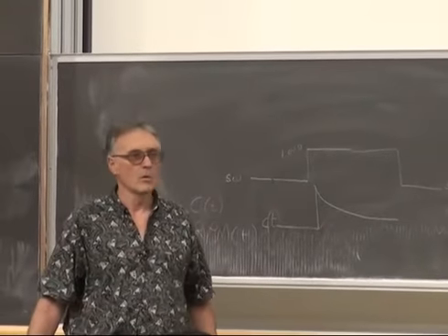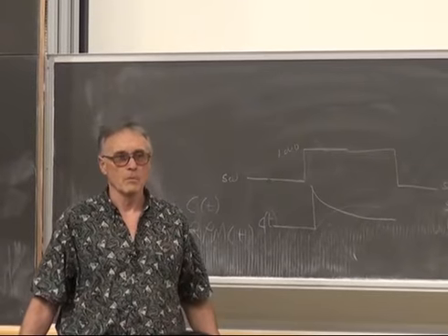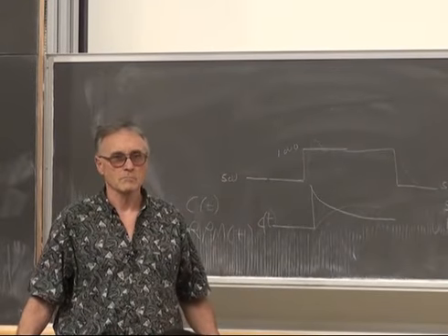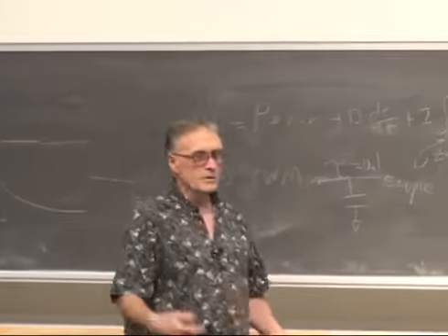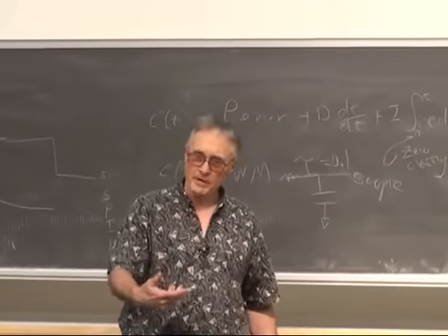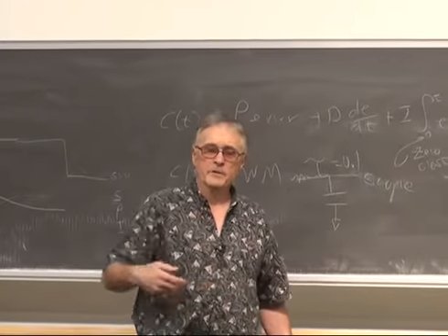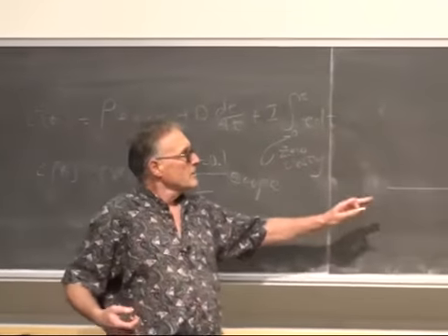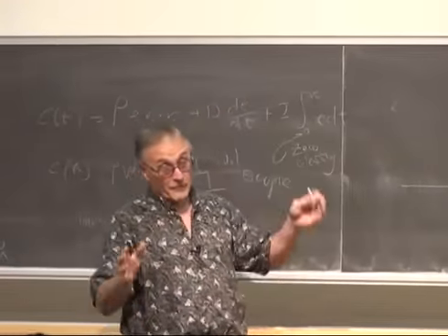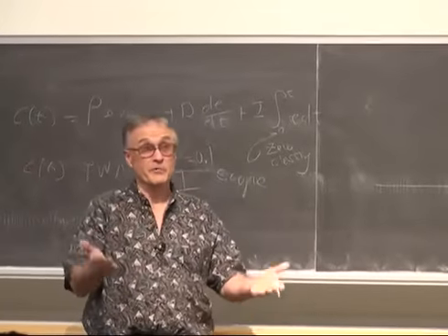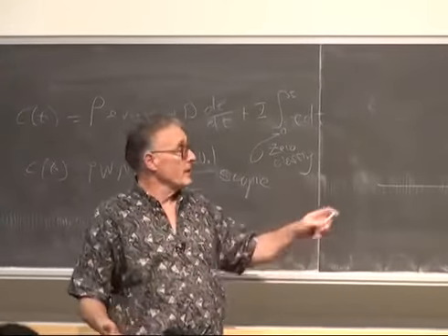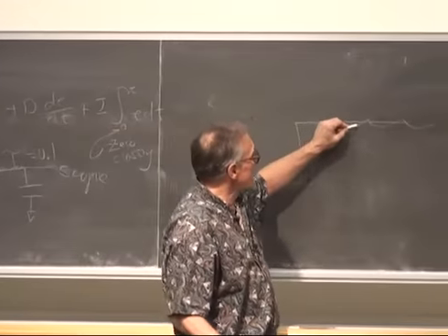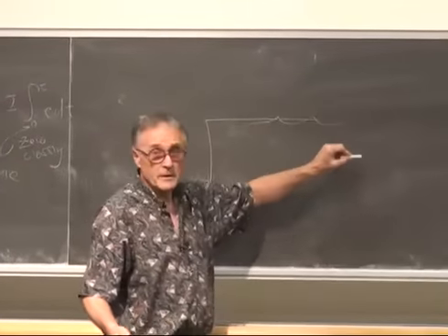Why do we need to reset the integral at all in this case? It's not winding up. Error. So integrals tend to drift because of error. I mean, if you have a bilaterally symmetric control system, if you can make the voltage negative to pull it down again, then you expect to get more like a sinusoidal oscillation across here.